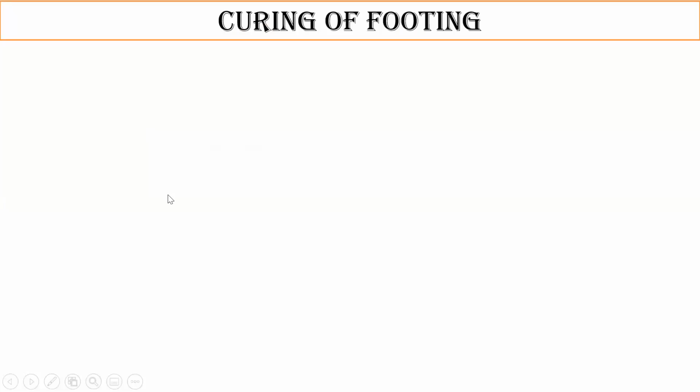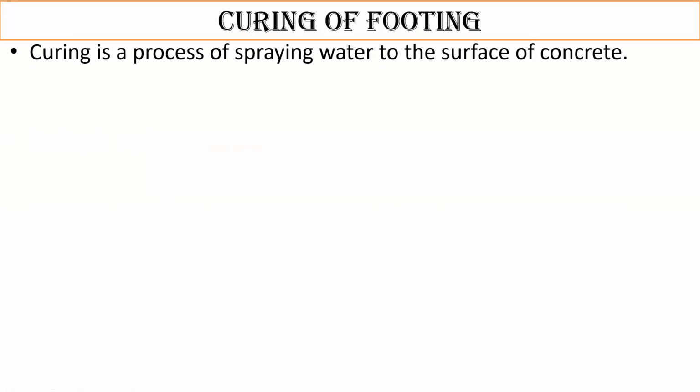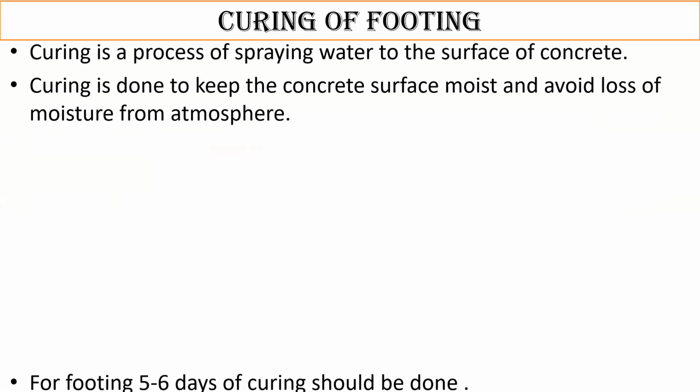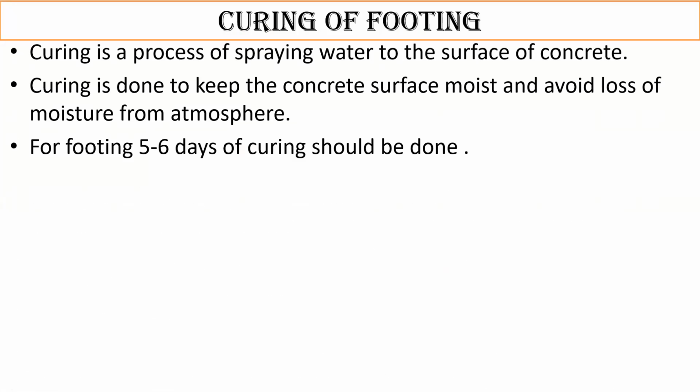So finally, the curing of the footing. So what is curing? Curing is a process of spraying water to the surface of the concrete. Curing is done to keep the concrete surface moist and avoid loss of moisture to the atmosphere. For footing, usually 5 to 6 days of curing is done. So what is curing? It's a process of spraying water to the surface of the concrete.